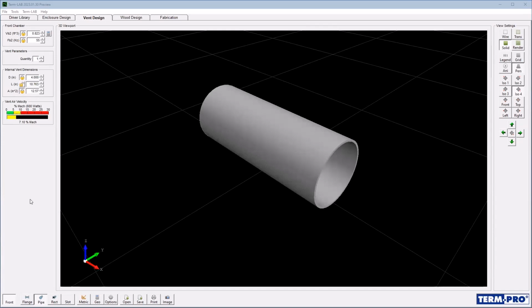When you try to tune a small vented box to a low frequency and the sub handles thousands of watts of power, you just might end up with a situation where you can't get it below 11 or 12 or 13%. So as you make the vent area larger, the vent length gets longer, but the port air velocity gets lower.